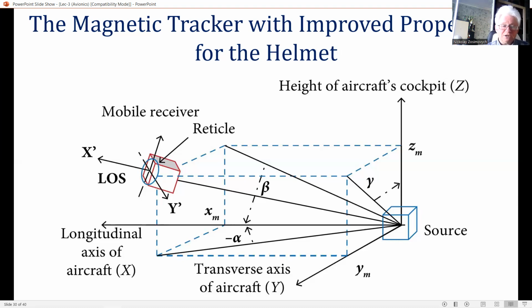Tracking errors of over 2 degrees have been measured under replicated buffeting tests carried out on the ground using tape-recorded flight data. Some specification of the vibration environment can be gained from the fact that a sinusoidal vibration of half G amplitude at a frequency of 2 Hz corresponds to an up and down motion of plus or minus 31 millimeters.